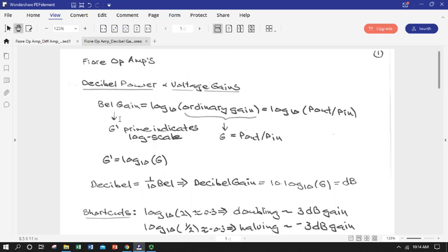and then we're going to modify that power equation a little bit using properties of logarithms and derive an equation for voltage ratio for equivalent power. So this is a little bit like RMS, where it was equivalent power. And this should be looking an awful lot like half power frequencies that you may have looked at in resonance. So decibel gain is primarily intended to convey some measure of how much power we're increasing or decreasing with our circuit.